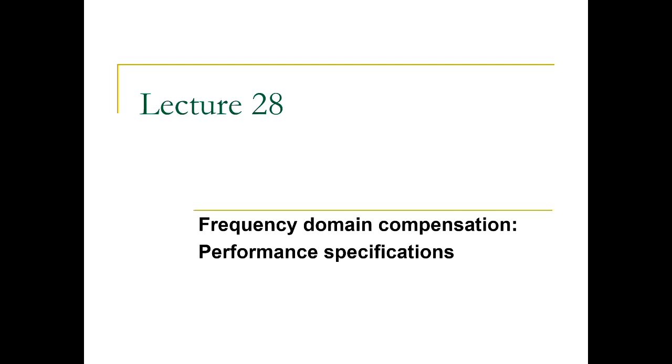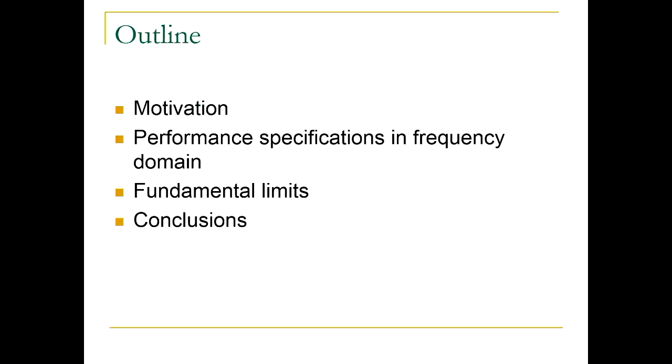All right. So as usual, I first motivate things a bit, then I will talk about performance specifications in frequency domain. You will see that you can, for instance, relate the shape of the Bode diagram to perhaps rise time or overshoot.